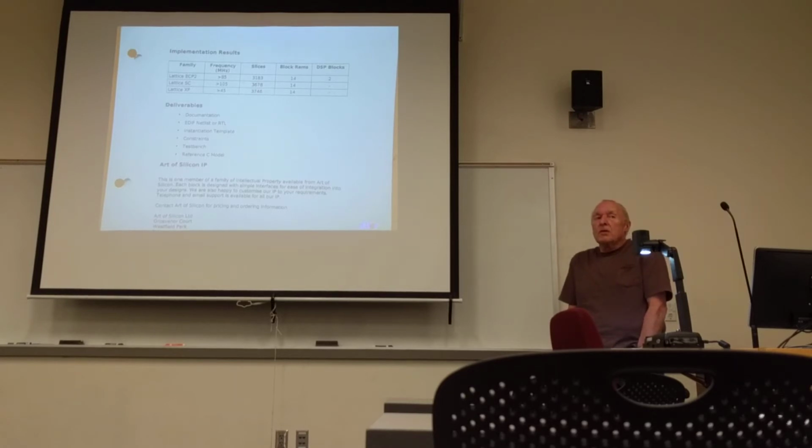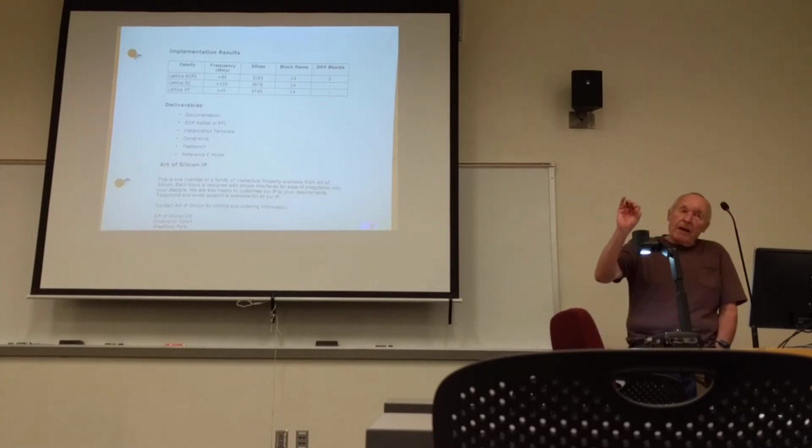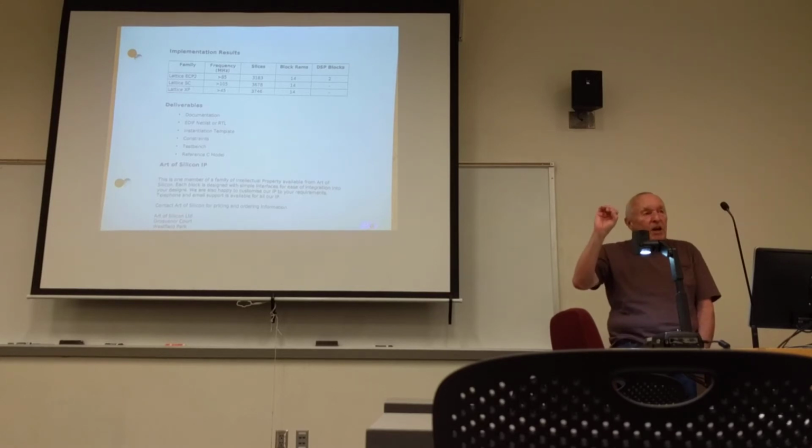Simpler. It's hard IP, as opposed to distributed RAM, where you're building up a RAM using LUTs out of the FPGA fabric. Block RAM is hard IP. It's a memory chip in every sense of the word, separate from the FPGA fabric. You have to instantiate it, but that's what they mean by block RAM. You got to make sure that you understand the concept of distributed RAM and block RAM, because it comes up over and over again.